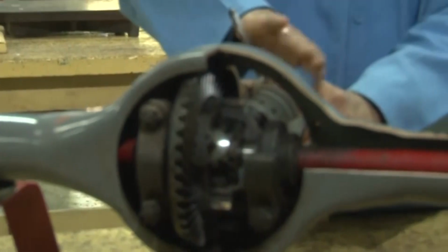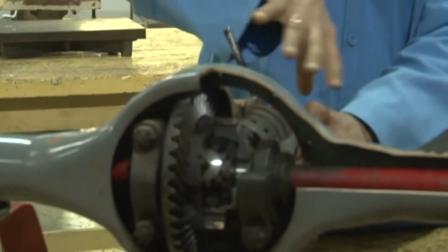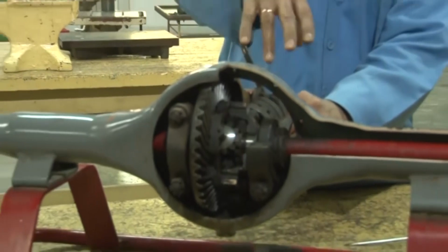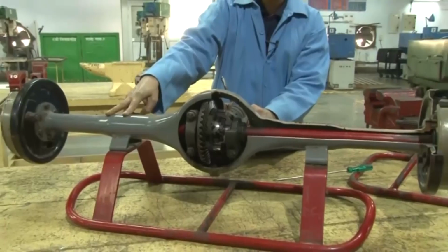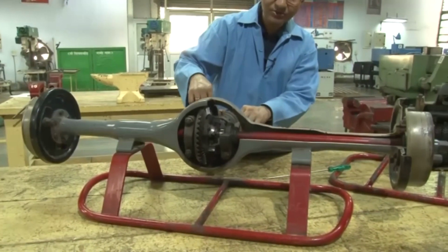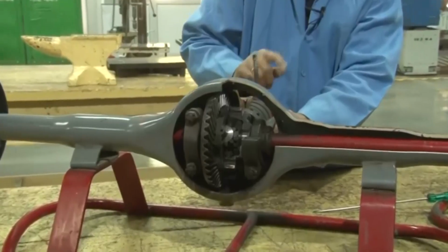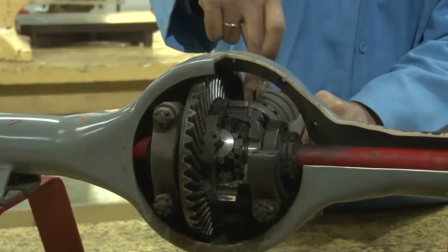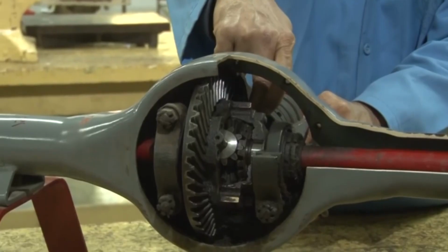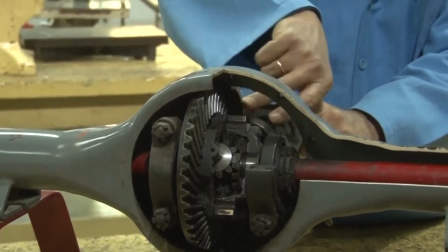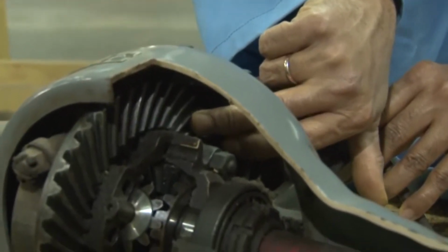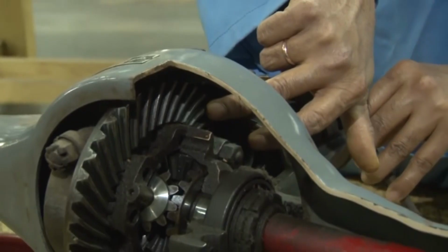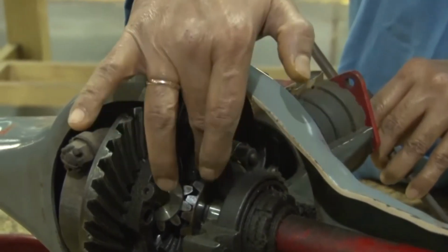And you can see here in this mechanism, this is the input shaft from where the power is transmitted to the axle of the rear wheel where the transmission goes in, and as you rotate here, from the input shaft through the spiral gear, it is connected to another spiral gear of the output shaft, okay. And this spiral gear of the output shaft is connected to other gears with the planetary drives.